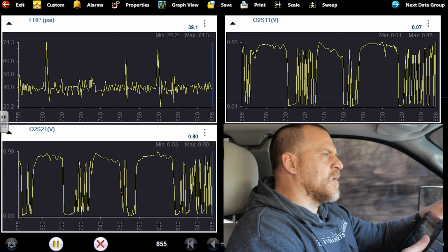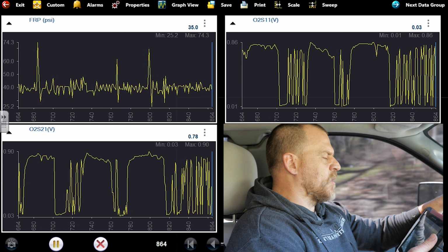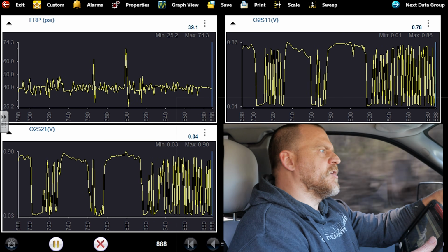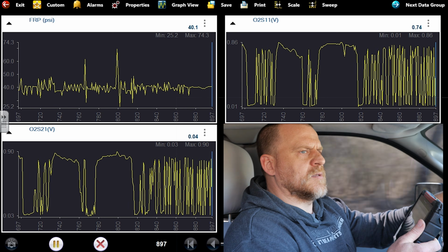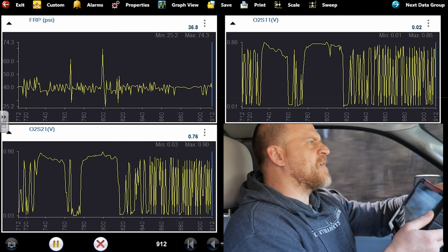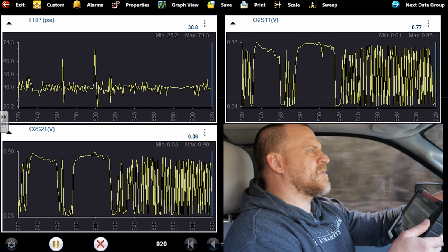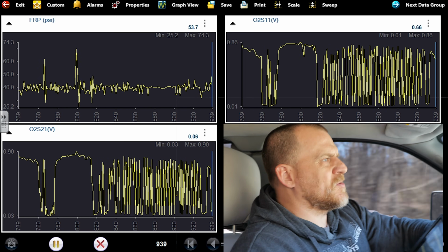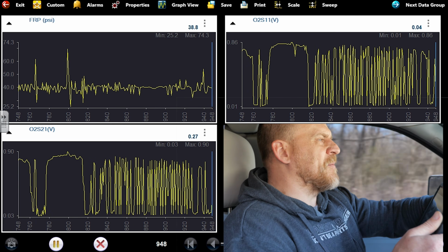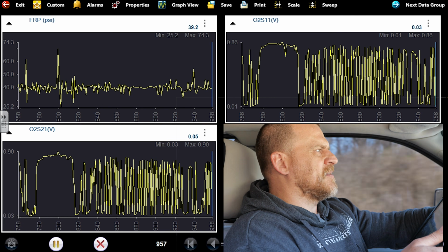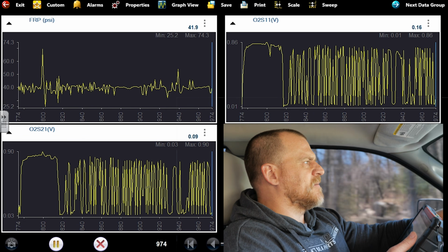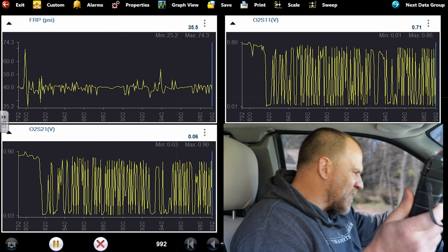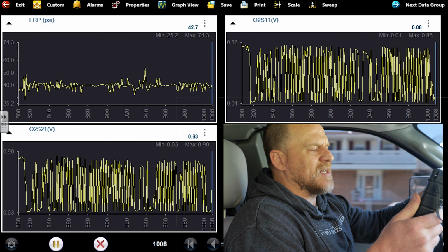I anticipated when we started that we were going to be dealing with a fuel rail pressure sensor problem because, you know, the pump's new and I just figured somebody maybe made the wrong call there. But the fact that we had lean O2 faults on bank 1, I realize bank 2 showed rich, but lean O2 faults combined with MAP and baro intermittent, and fuel rail pressure range performance, this could easily be a failing pump, and we just need to get it a little bit warmer.